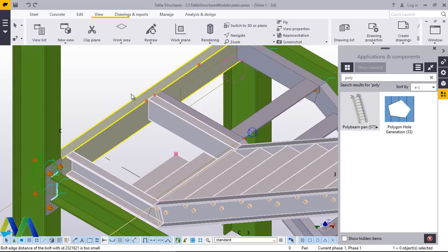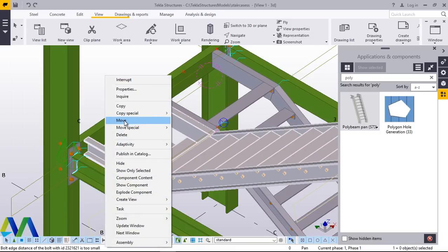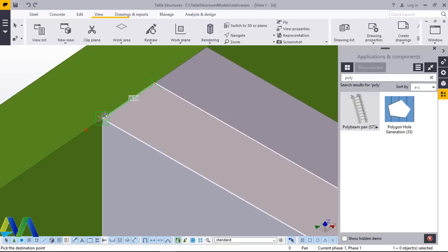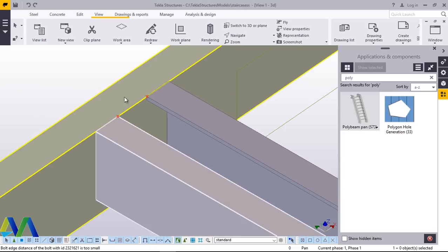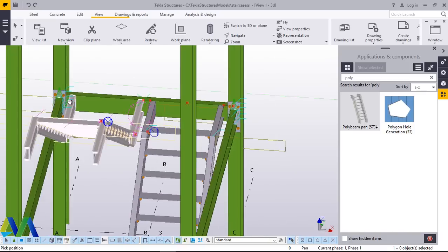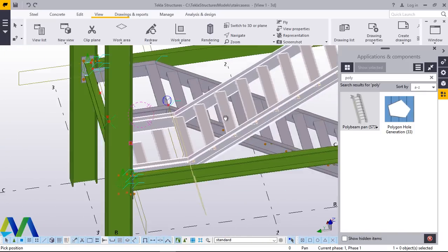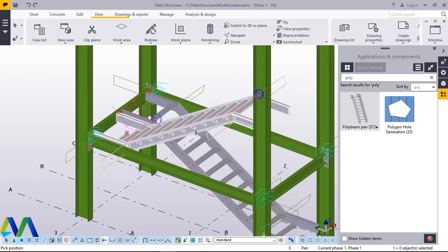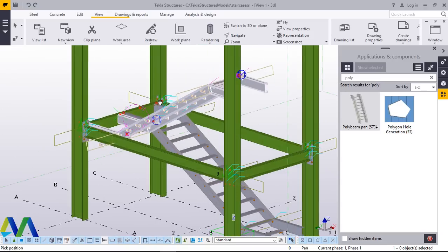Now from there, I'll right click again and give it an offset of 100 millimeter. I'll snap there and just direct my cursor and place it there. Don't click, then type 100 millimeter on your keyboard. Then come to navigate, rotate with the mouse and turn this round like this. We've made our staircase, but this is just the first step.